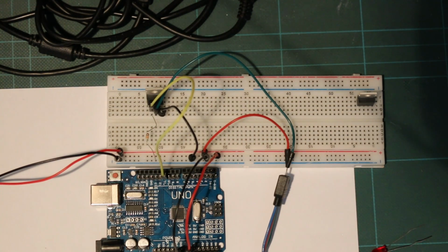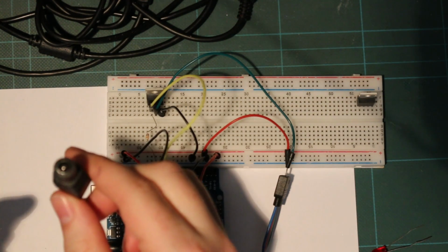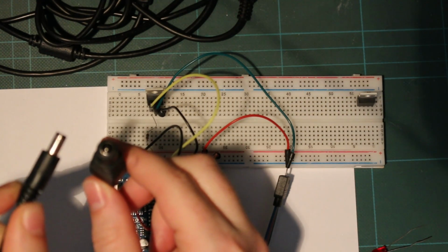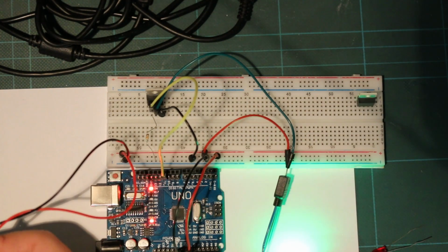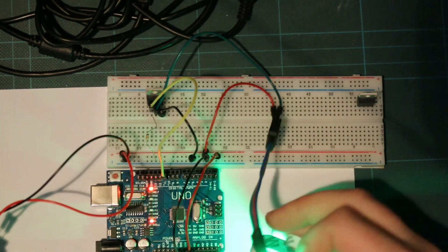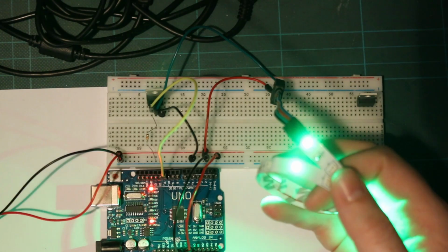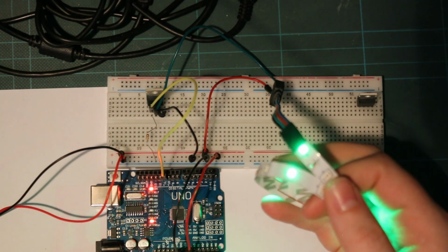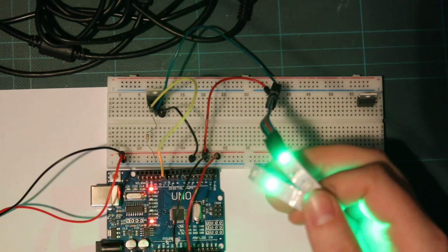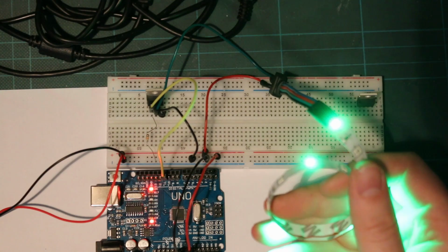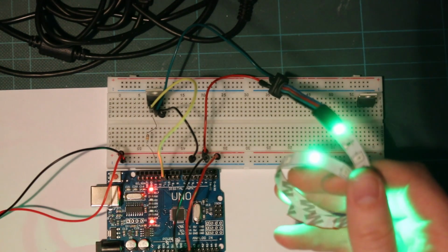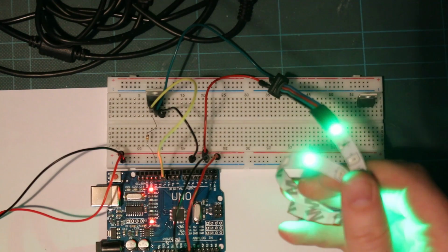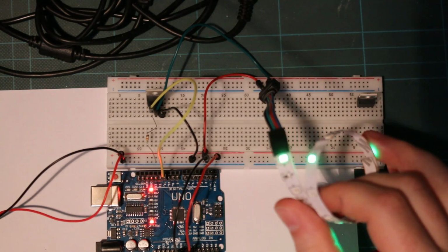So now let's give it a quick test run. As you can see here, I'm just going to be plugging the standard 12-volt plug into this 12-volt jack, and hopefully, if I'm not mistaken, here we go, we have our LEDs. And I'm running the same code as before, where I was fading the LED on and off. So I'm changing the brightness. Exact same principle, fairly straightforward I think. The only difference is we are now doing it with 12 volts.